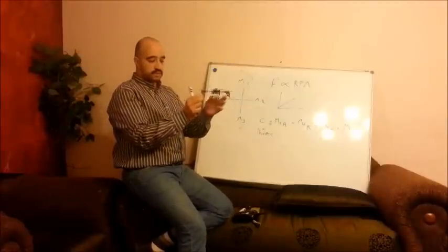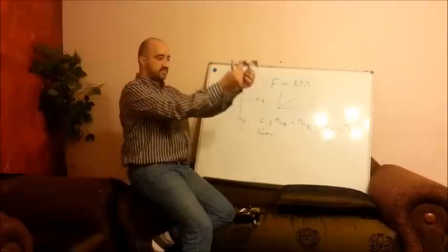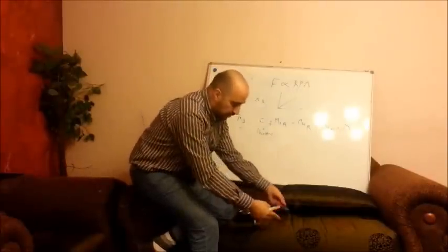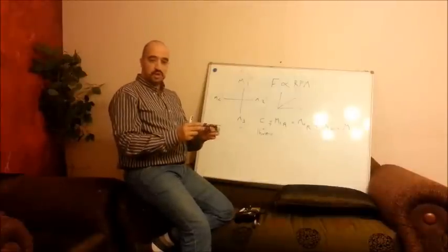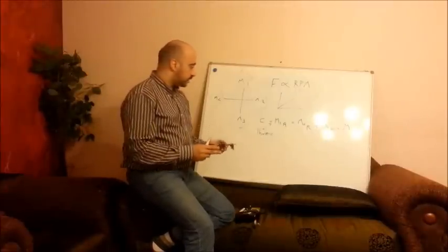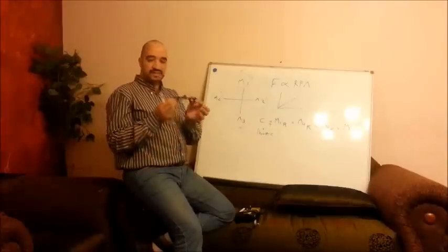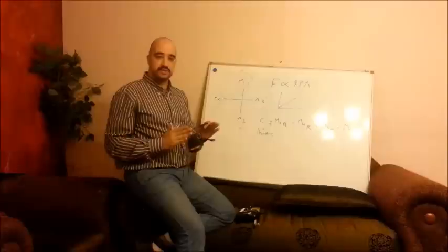Now let's consider that we give it thrust and the quad is flying now. Actually, without balancing, the quad will flip like that and it will never fly. It needs a gyro at least to be able to fly. Why? Because there are no identical motors. There is nothing called fully identical objects.